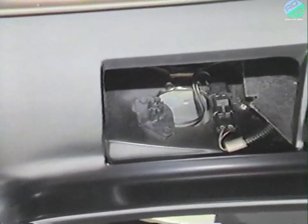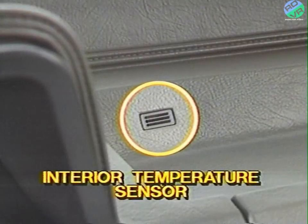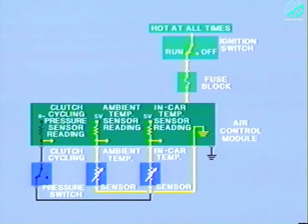The ambient temperature sensor is located on the right radiator support bracket below the front bumper. The interior temperature sensor is located at the front of the instrument panel, just left of the glove box. These sensors are really thermistors that the ACM sends a 5-volt reference signal to. As temperature increases, resistance increases at the sensors, and the amount of voltage drop detected at the ACM internal resistors decreases, allowing the ACM to calculate temperature and adjust heating and cooling accordingly.